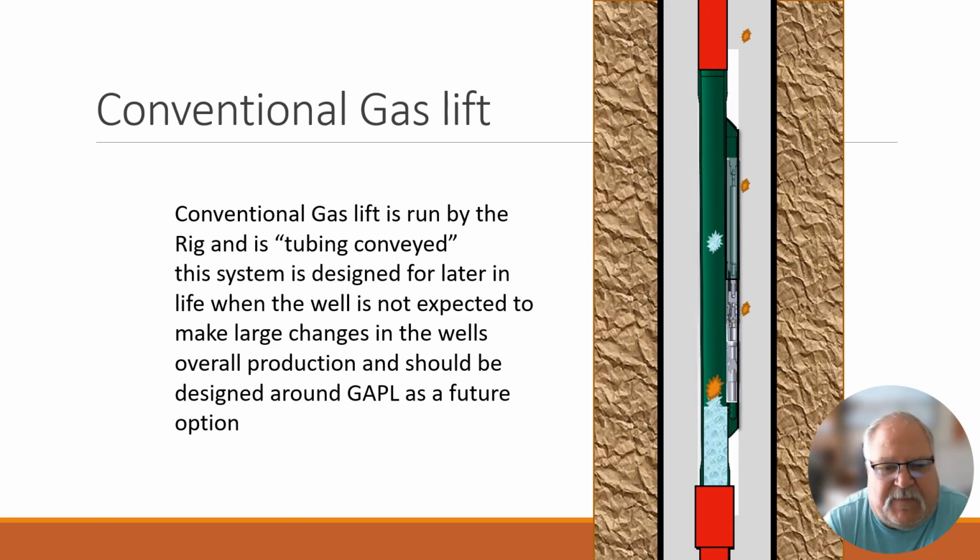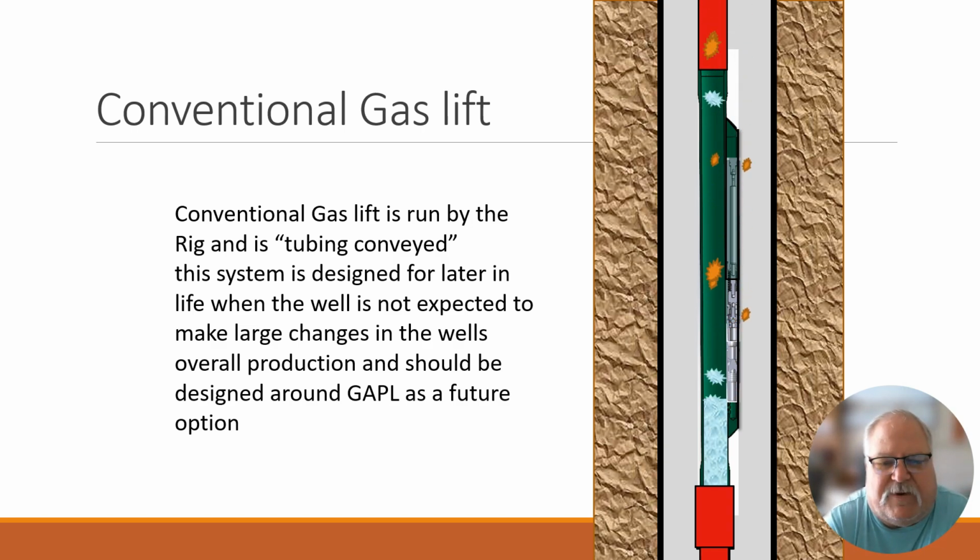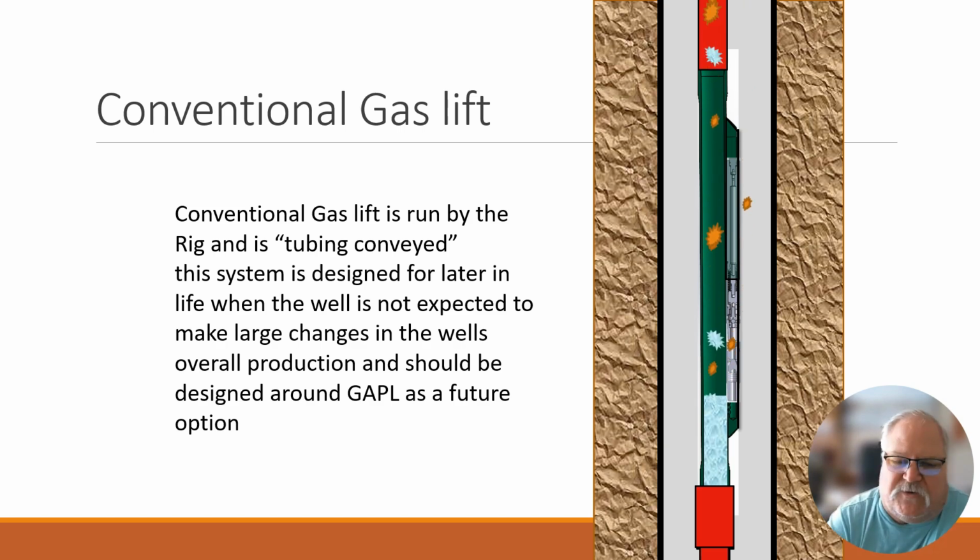And then basically what happens is the bottom hole pressure of the well is going to push the fluid up hole. Now initially the well is going to have all sorts of high bottom hole pressure, so it can push a fluid column way up in the well. So that's why you have upper valves. There's no point in having upper valves if you have no bottom hole pressure. Putting more valves in for low pressure does nothing, because the liquid doesn't get to the valves anyways.